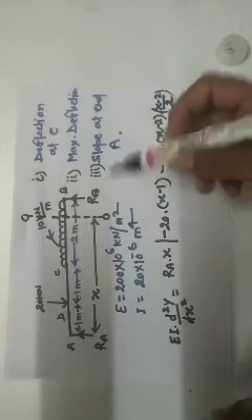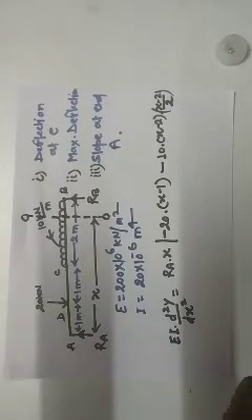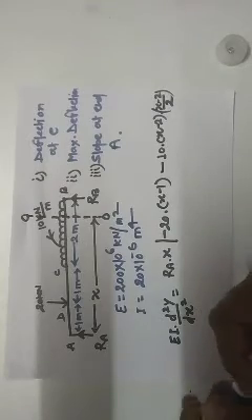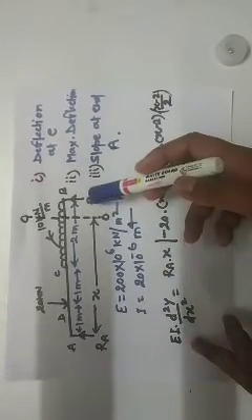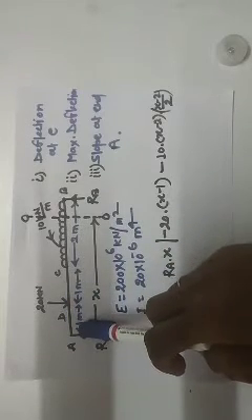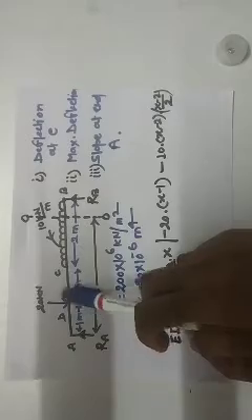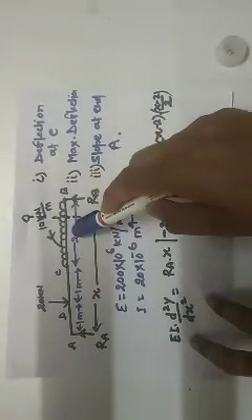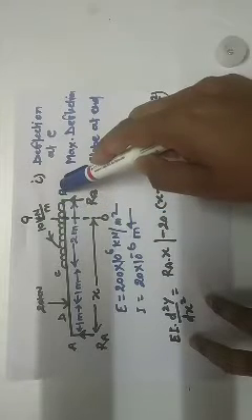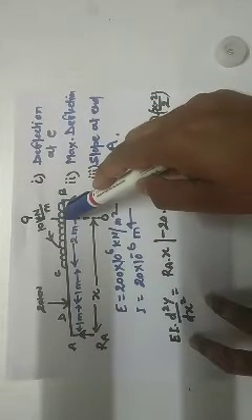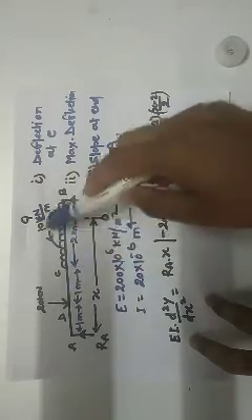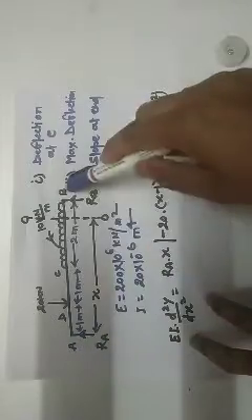For deflection of a beam, we must know how to calculate the reactions at the supports of the beam. So this is 20 kilonewton, at 1 meter from end A. And 10 into 2 is 20 kilonewton acting at a distance of 1 meter from end B. Both 20 kilonewton loads act in the downward direction and are equidistant from their supports A and B.